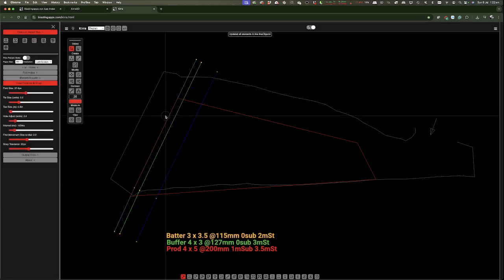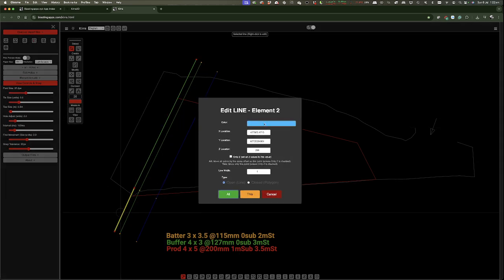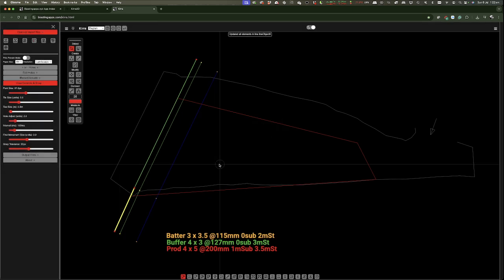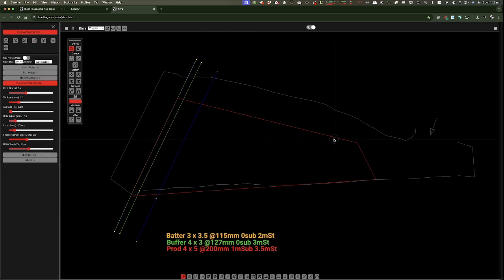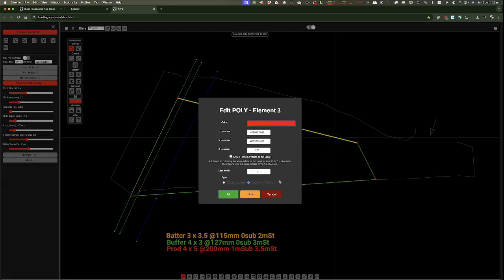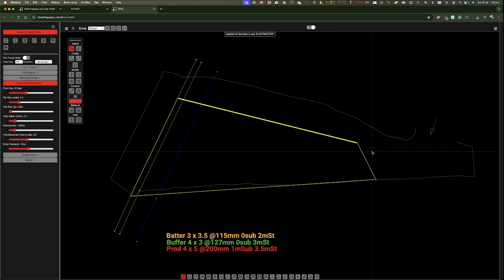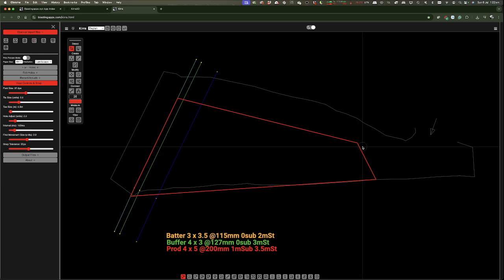Alright, so that's green, and this top one here we'll make, I don't know, cyan. There you go. We've got this blast polygon here that we're going to design inside, and we can dial that up to 3 thickness, and its elevation's incorrect, so maybe we want to put it at 286, which is the crest, and we tick that box and we can go okay. And now that is at that elevation.